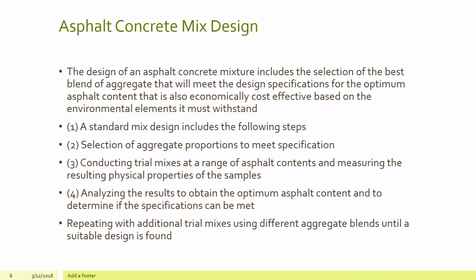Asphalt concrete design mix. The design of an asphalt concrete mixture includes the selection of the best blend of aggregate that will meet the design specifications for the optimum asphalt content that is also economically cost effective based on the environmental elements it must withstand. And we discussed this already. Different parts of the country are going to have different specifications and standards to handle the environmental conditions that the road surface is going to be placed within.